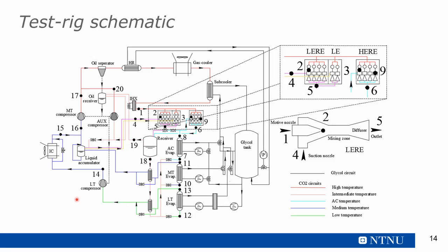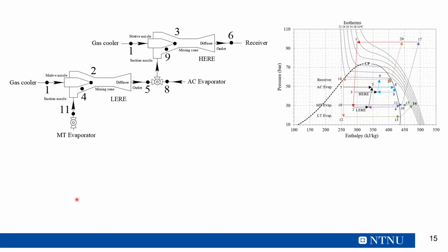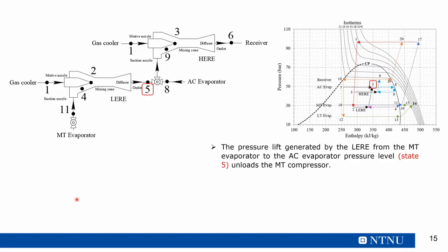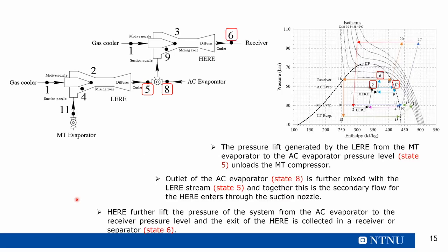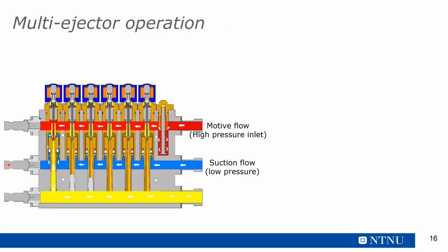And there is also an option to explore the possibility of having a parallel ejector, which is not very familiar nowadays in the study, but definitely there is a possibility to handle 2 parallel ejectors in the unit, and extraction could be easily identified. And you might have already seen how these ejectors are designed from the internal side, but now to have better capacity handling, Danfoss is offering a number of cartridges. In this, you could see 6 different cartridges in a single ejector, which is capable of handling varying load and different types of capacities of the unit. So this is one which you will easily observe in the unit, which is available in IIT Madras.